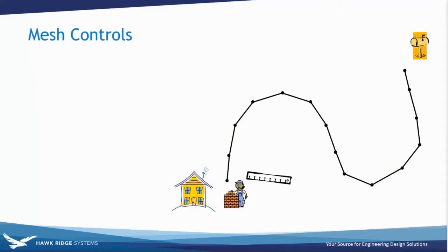So in this example, those linear segments of the line can be considered our mesh, with each line segment being a single element. The more elements we have, the more terms in the equation we would have, causing a longer calculation time. So the mesh directly influences the solve time of our solutions. The more elements a problem has, the more equations are needed to solve it, therefore increasing our solve time.